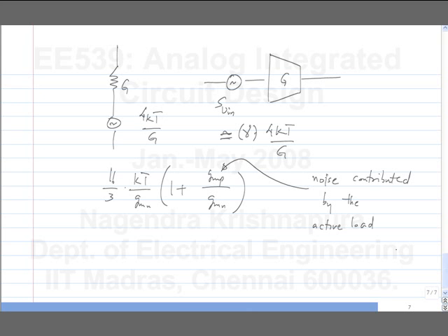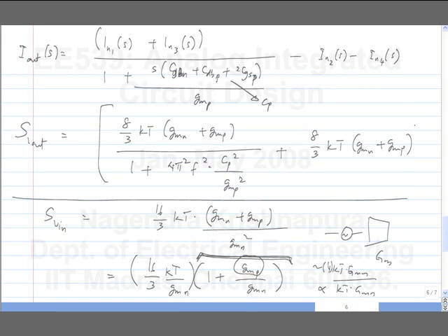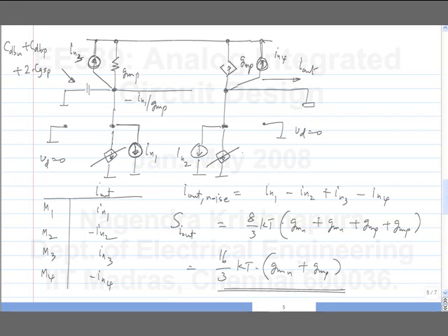Okay. And you can also calculate it for high frequencies. You simply divide this by the high frequency transfer function. So, I think some of you have done it only for DC, many of you have done it for the AC case, but what some of you have done is to calculate the current noise output at DC, but divided by the overall transconductance, overall transadmittance as a function of frequency.